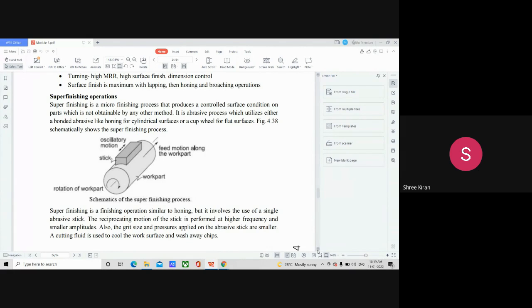After the gear grinding process or the gear finishing process, in some cases we will have a super finishing process. All of this is to achieve the maximum surface finish accuracy and better dimensions. When the gears mate, there should be no error that results in rubbing action, vibration, or chipping of the teeth, where metal gets removed from the teeth and the tooth dimensions or shape change. To avoid or eliminate all these aspects, we do these operations.